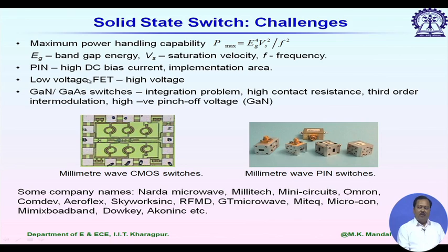Next, for FET, the problem is its lower power handling capability. For high power applications, we can't use FET switches, but the advantage of FET switch is its low power consumption compared to other switches. Similarly, gallium nitride or gallium arsenide switches, although they provide better figure of merit compared to FET switches, we face integration problem, high contact resistance.